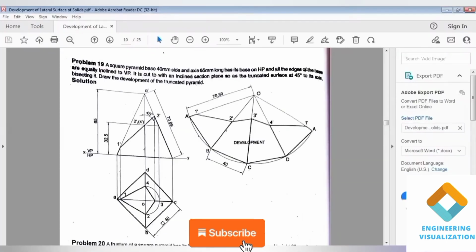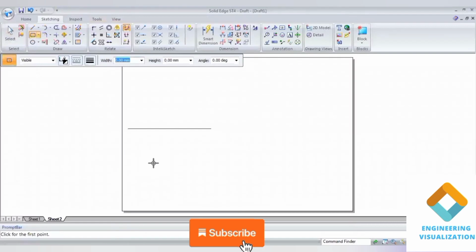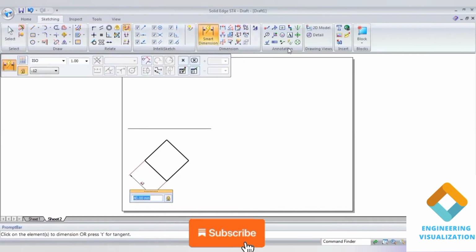So go to rectangle by center. Here the width and height we have to give, that is 40 and 40, and the angle will be 45 degrees. So this is how we construct the square with respect to the corner position. Show the dimensions and write down the names for it.